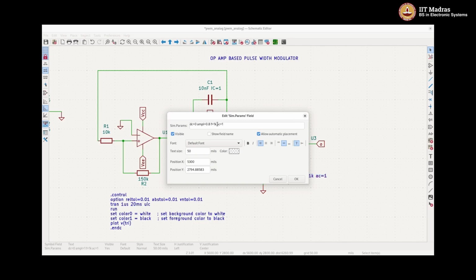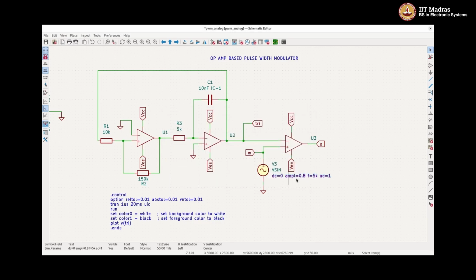I will go 1/10 of that frequency for the modulating signal, let's say 5 kilohertz, so that you will be able to see it in the display without zooming directly. 5 kilohertz sine wave, the modulating signal. The triangle is generated at what you get is approximately 57 kilohertz or something.